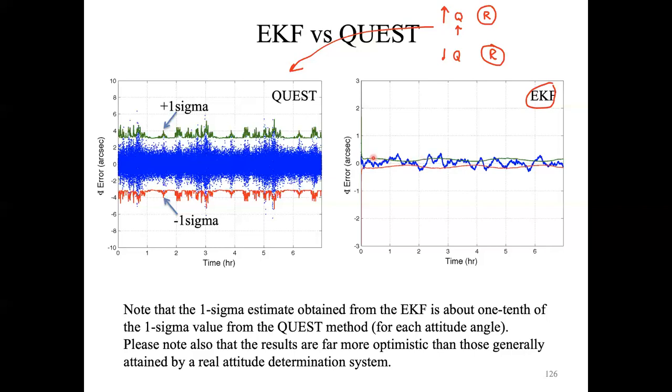But this is a general problem that you always have with the Kalman filter, because the Kalman filter not only includes the observation that you have at that specific instant, but is propagating the information that you got previously. It is always affected by the fact that the stability of the method is going to get worse at a certain time. So for example, after 1 hour, probably a reinitialization of the filter could be indeed useful.